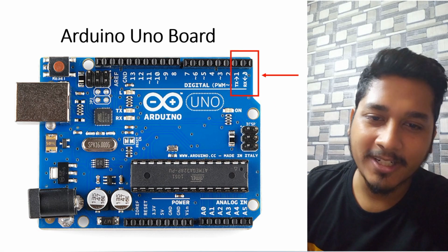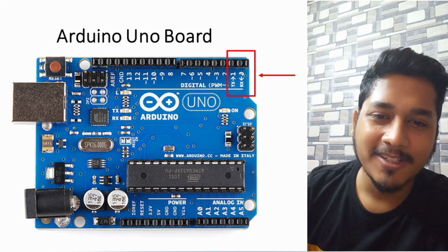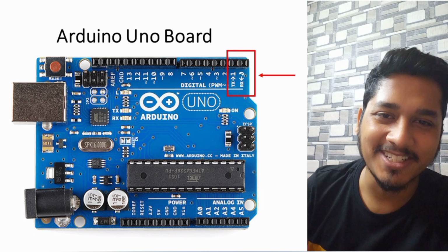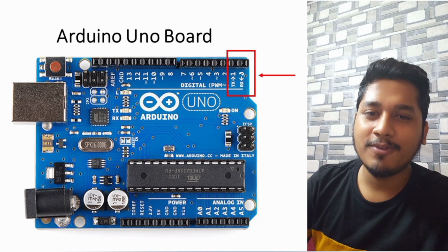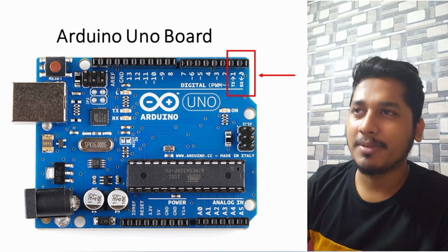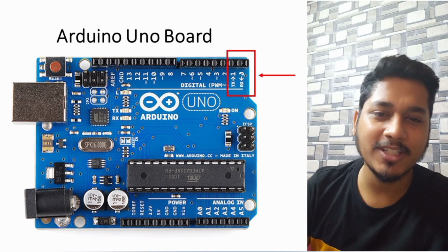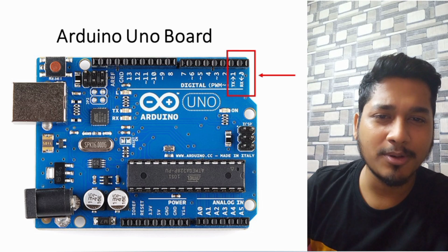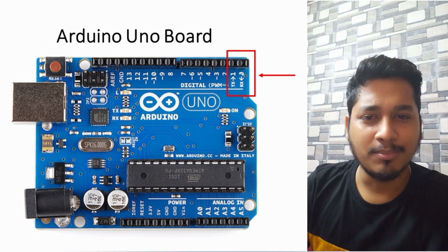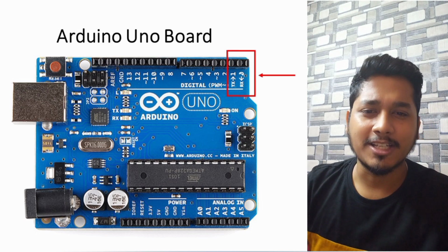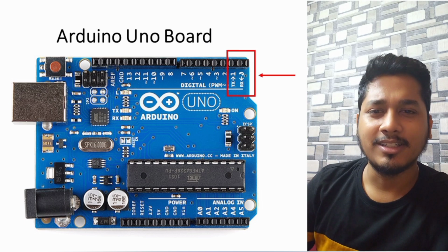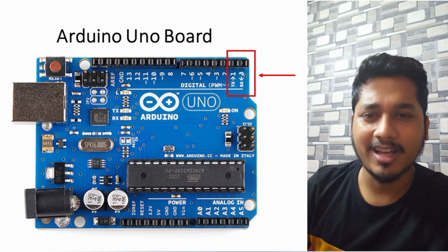Arduino provides 14 digital pins. Among those, the first two of them are used for serial communication. For example, if you want to build a smart system, say we have developed a mobile application using the Bluetooth protocol, and we want to control our Arduino using Bluetooth. So we will be transmitting data using Bluetooth, and the Arduino will turn the switches of our home accordingly.